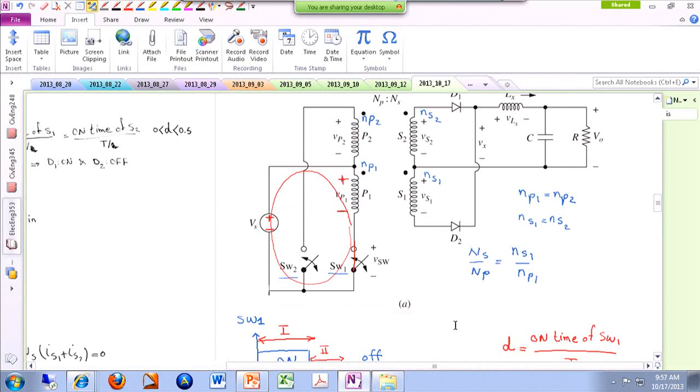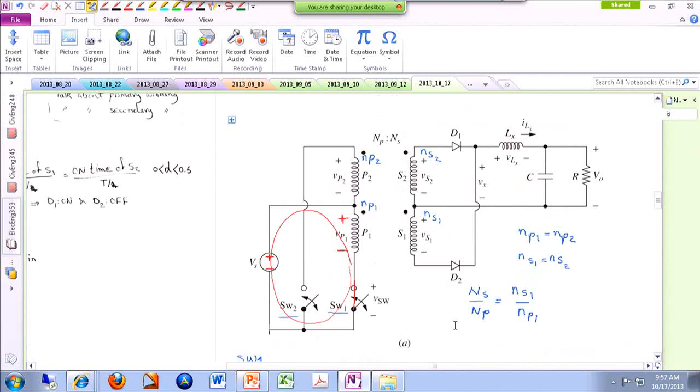So now we have to figure out what happens to the diodes, diode number 1 and diode number 2. So remember, we bring back the rectifier mentality. Let me erase this a little bit. So if the primary side voltage is positive, that means this voltage is also positive, and this voltage is also positive. Now, going back to those rectifier circuits that we studied earlier, this is a center tap full bridge rectifier.